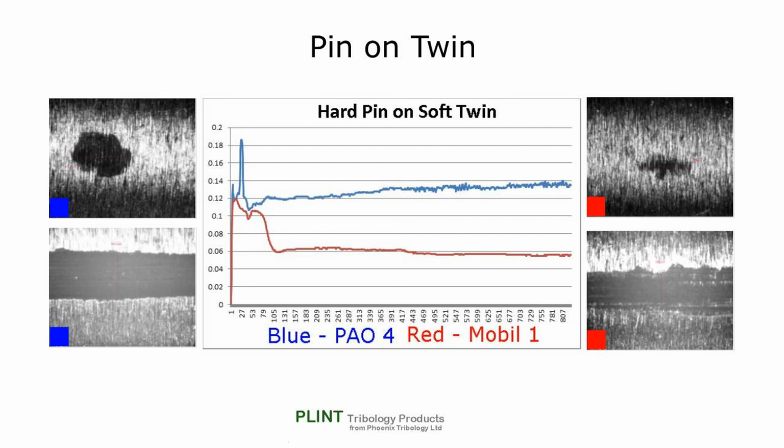The wear scars on the pin sample are not readily measurable, with the base fluid scar showing witness marks corresponding to stroke end contact, and the fully formulated lubricant producing witness marks indicating a line contact.